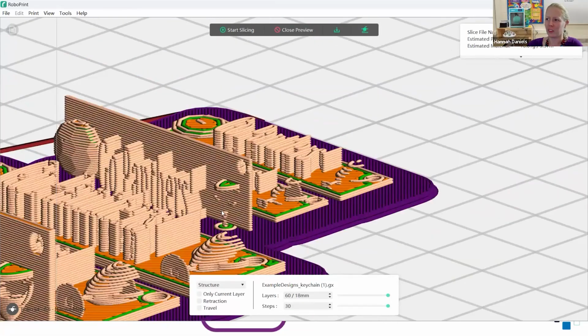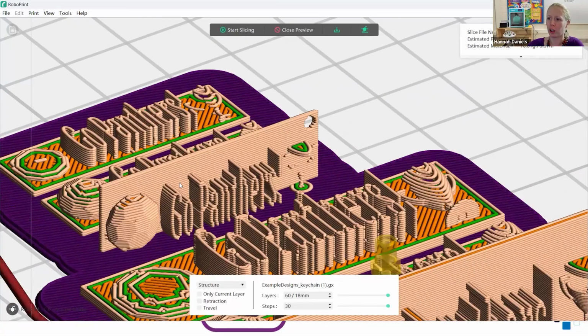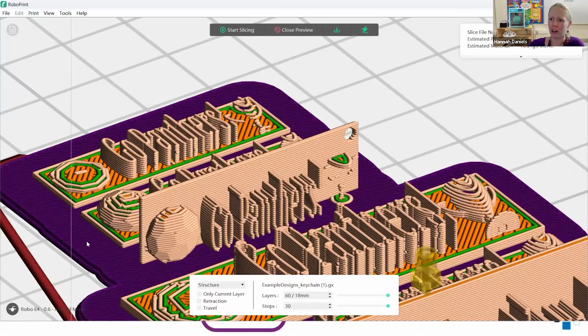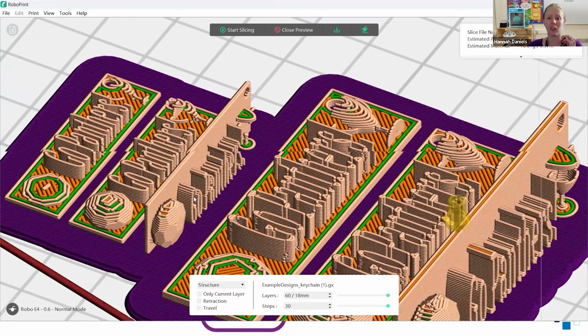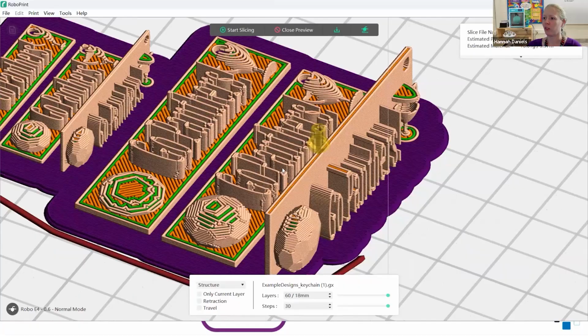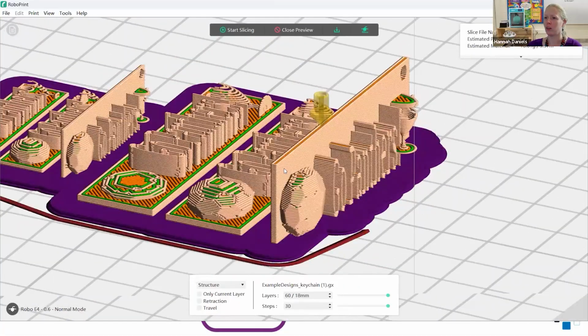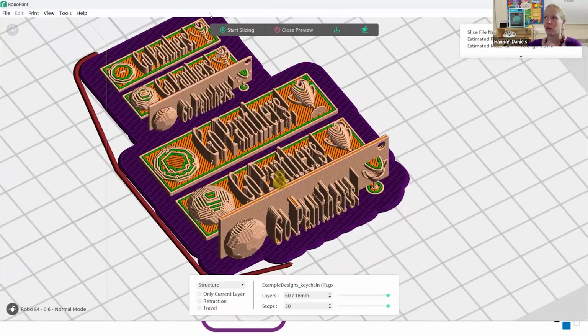This one, again, the trophy is just too thin, but you can now see that there's actually a soccer ball shape to this, which I'm not really getting with this. So this slice preview is giving me a lot of good information. And as I look at the larger ones, I can also see in more detail what I'm getting out of this. So using your slice preview as another troubleshooting step is a really good way to give you an idea of what you're going to print.